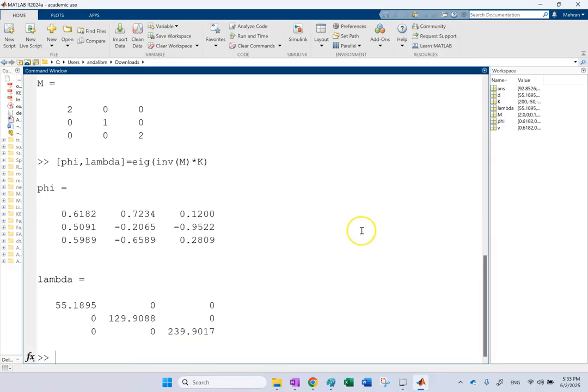There we go. So these are the eigenvalues, of course written as the matrix, so all you care about are these diagonals. And these diagonals, remember, are not natural frequencies, these are natural frequencies squared. So you have to take a square root of them to find natural frequencies.